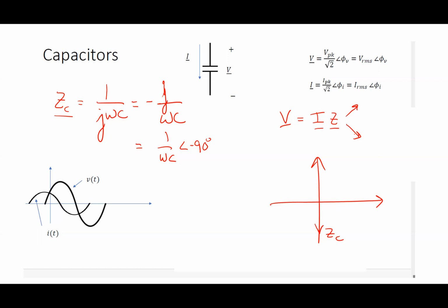What's the magnitude equation if I have V equals I times Z? So one vector equals one vector times another vector. How do I relate the magnitudes of those vectors? The magnitude of V equals what? Magnitude of I, yeah, times the magnitude of Z. Okay. What about for the angles? Yeah, they add, basically. They add algebraically. If I had divided, then there would have been a subtraction, right?